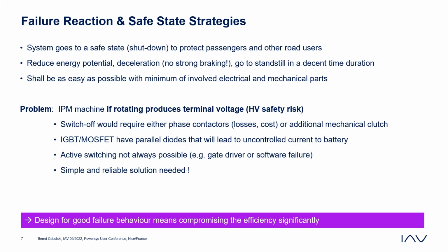You could use a contactor on the AC line, but you could imagine if you're running 800 amps, it would be quite a big device to really mechanically disconnect the AC lines. And the reliability on those switches needs also to be very high. So it's not really practical to do that. In industry, that's the approach they take. With EV, it's not possible.